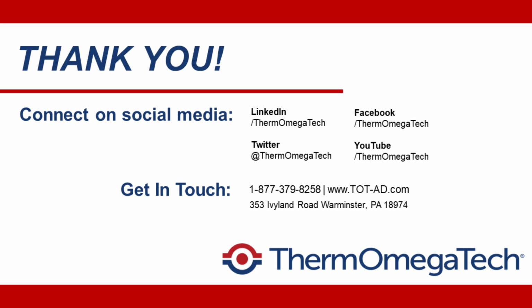Great. Thank you, Glenn. We'll now take some questions from our audience. The first question is, what is the accuracy of the temperature setting in the mixing valve? So it's going to be whatever your normal setting is, plus or minus 8 degrees F. So what will happen in the mixing valve, let's say for a 100-degree mixing valve, if it's set at 100, it would go down to 92, maybe up to 108. But what happens is it usually finds its own sweet spot during mixing. But if it's for diverting mode, it'd be the same thing, between 92 and we'll say 108.